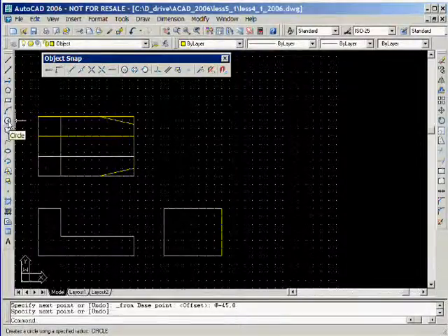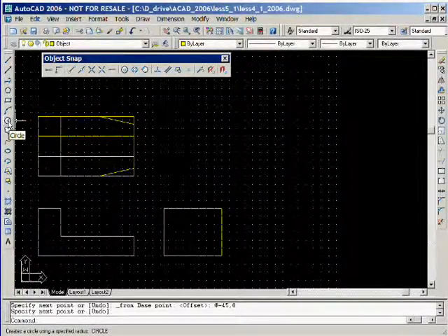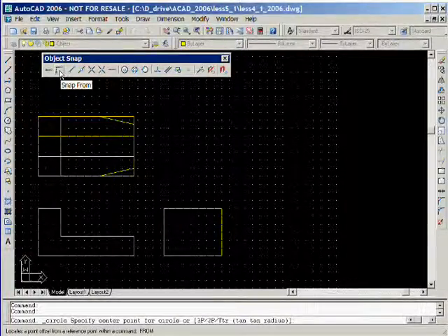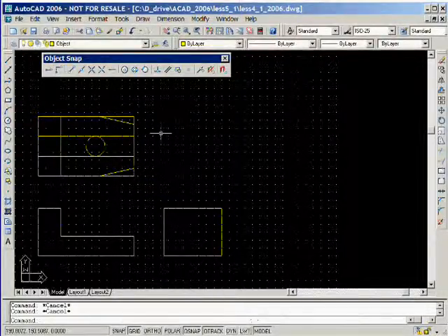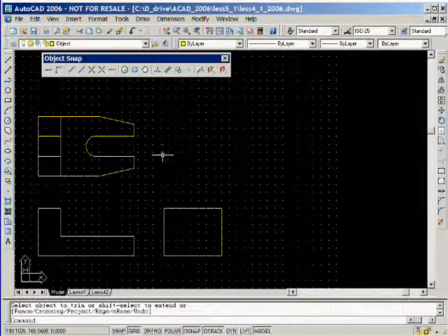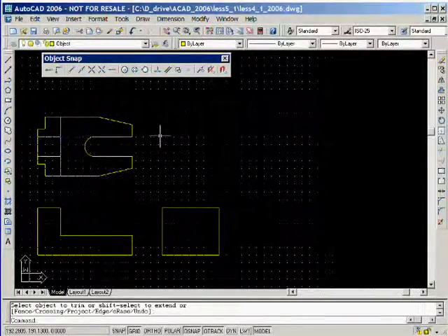This process is repeated relative to the upper right corner in order to create the sloping line at the top shown here. We'll now create a 25-unit diameter circle by also using the Snap From icon to define the location of its center relative to the lower right corner. We'll now use the Trim option to clean up the top view as shown here. And then finally, we'll add several lines using the Offset option and then make use of the Trim option to produce the drawing shown here.